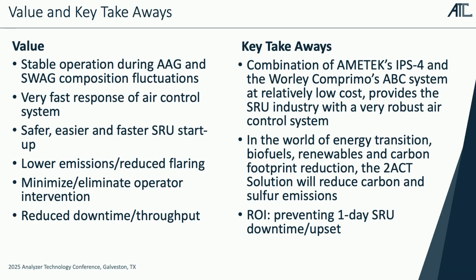And also, having this system, we minimize or reduce operator intervention for two reasons. One is the air to acid gas ratio would be a manual set point before, so may from time to time have to be adjusted by operators. This is now automated. Secondly, because we have more stable control, this would result in lesser alarms, lesser upsets, and lesser operator interventions, actually freeing up time for the panel operator to focus on other plants that are also in his or her span of control.